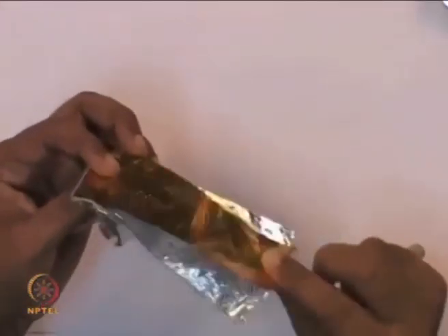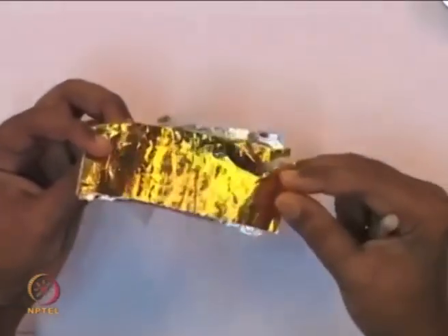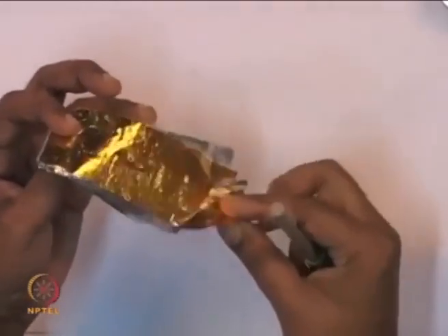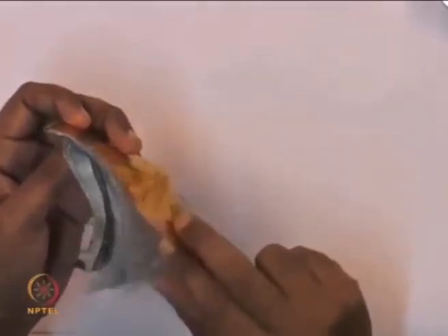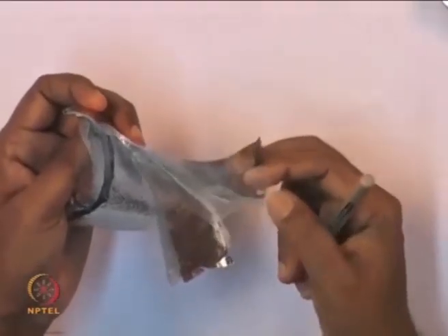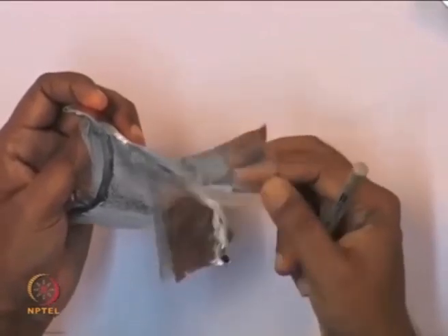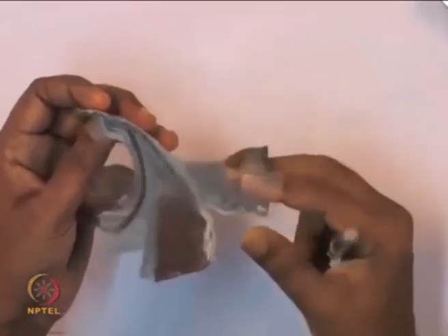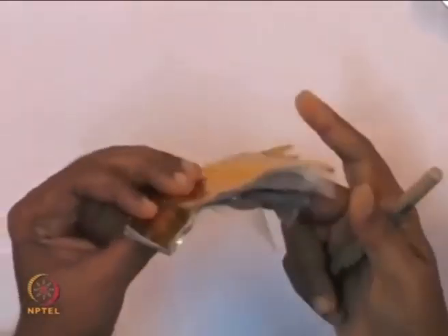What you can see is a very typical insulation called multi-layer insulation, and it has a highly reflecting surface like aluminum foil or aluminized Mylar. So, we can have a very highly polished surface, and we can have different layers of this. Each layer is separated by a non-conducting medium like nylon net. We can have some non-metallic material, such as nylon net, which separates the layers, and this is what is called multi-layer insulation.